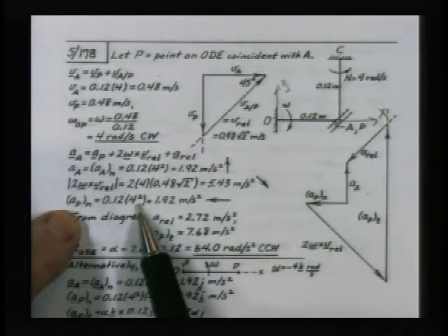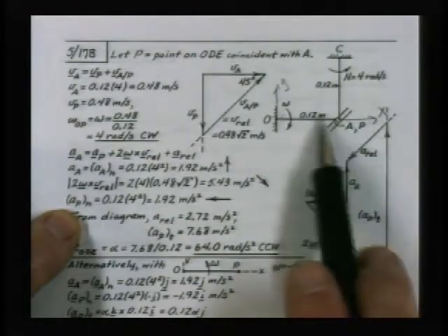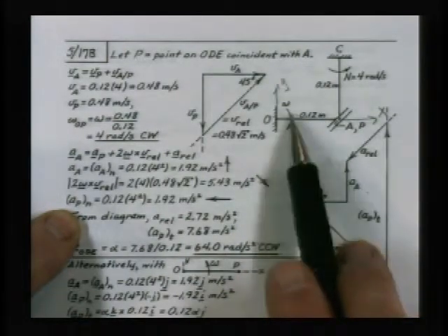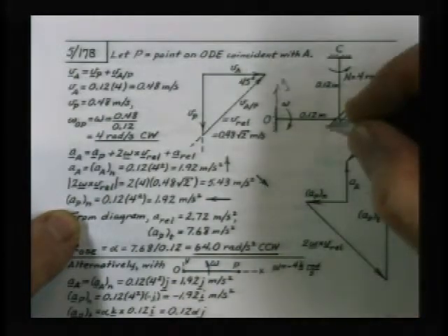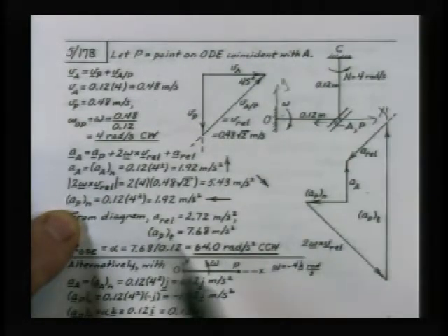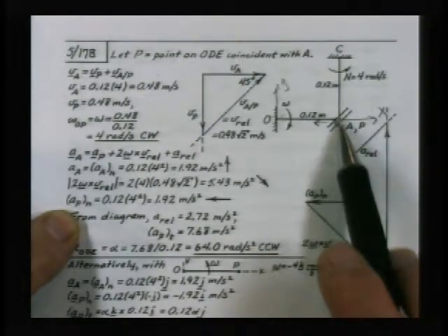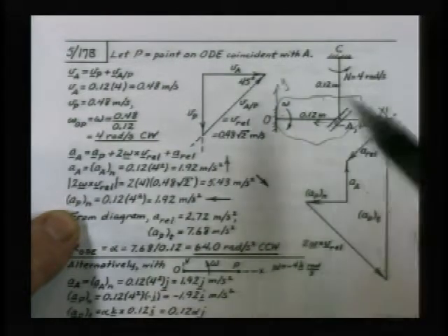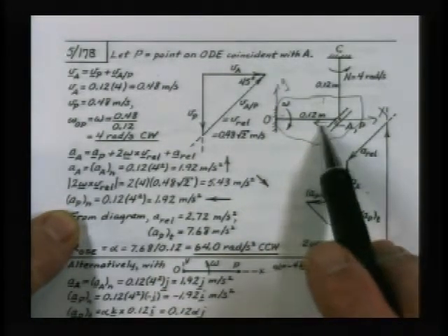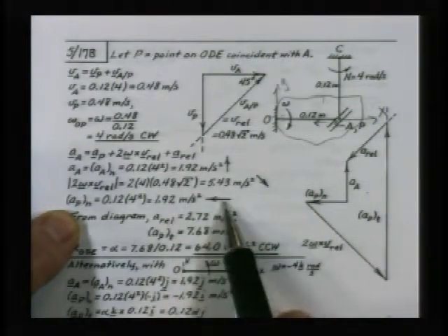here. This is the one I was looking for right here. Here's the acceleration of point P. It's this lever arm right here times the omega of this member. And here's our omega, unknown, and it points back to the left. So this term, acceleration of P normal, P is fixed on this plate. Here's this plate here. And normal is pointing back this way. And you can see that in their polygon right here. And they show it with an arrow.